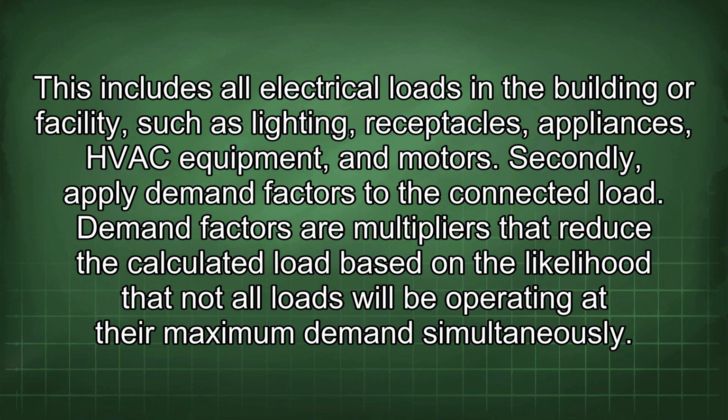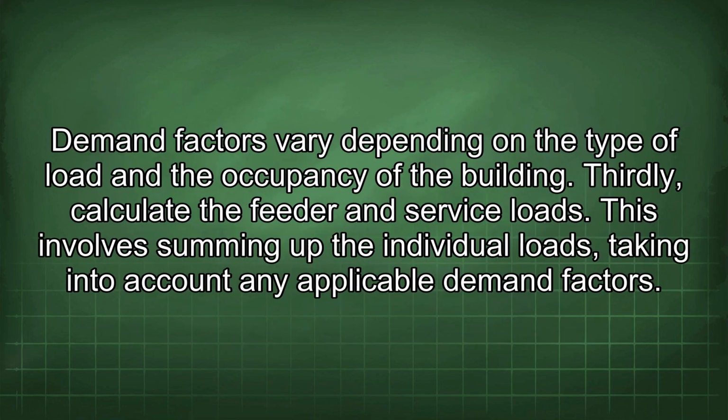Demand factors are multipliers that reduce the calculated load based on the likelihood that not all loads will be operating at their maximum demand simultaneously. Demand factors vary depending on the type of load and the occupancy of the building. Thirdly, calculate the feeder and service loads.